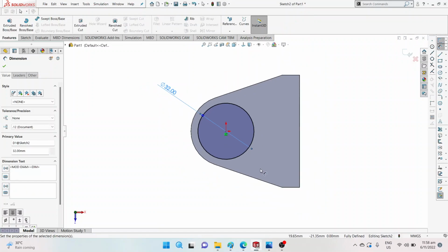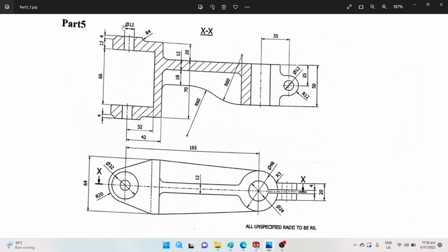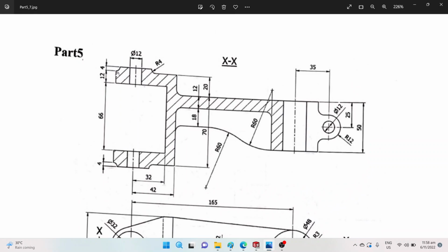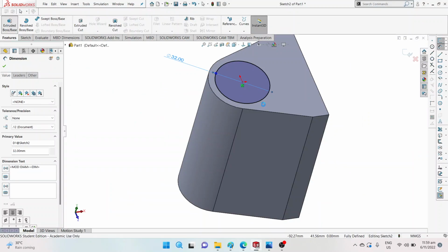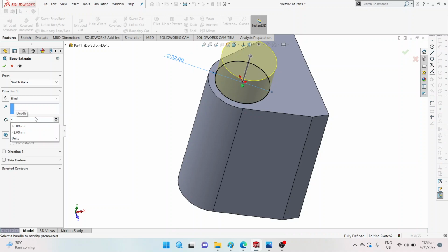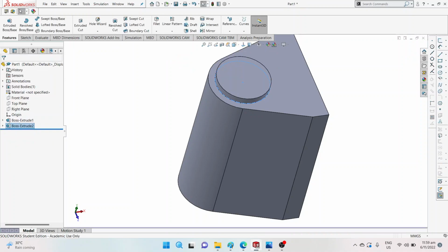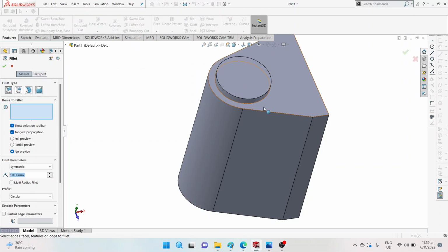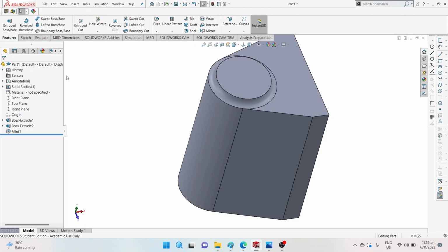And the height at which it's being extruded up is 4 millimeters in height. Okay, and then there's a little radius. So that is something that I have to take note of. So I'm going to extrude by 4 millimeters. I type 4, enter. Extrude by 4 millimeters, and then I'm going to add a fillet. Which edge do I fillet? I'll fillet the corner here, and the fillet radius is 4 millimeters. So once I have that, I'll have this fillet radius.